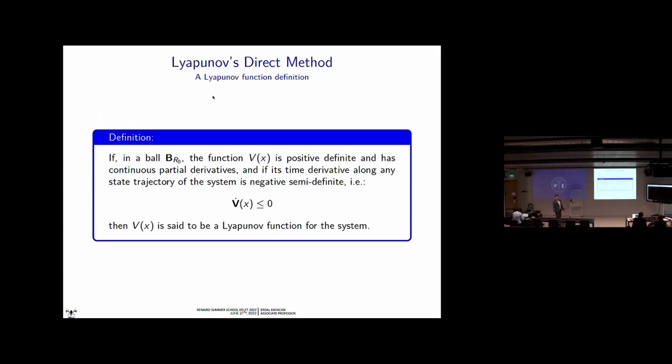Yes? So this is just a clarification. So this last condition is just stating that the energy has to decrease over time, right? This is the necessary and sufficient condition for choosing my Lyapunov function. Yeah, this rule, in the last fragment, yes, in an indirect way, it's related to energy. This condition says, for instance, you can't choose x minus y as a Lyapunov function, because this doesn't satisfy these rules. It has to be a certain function.